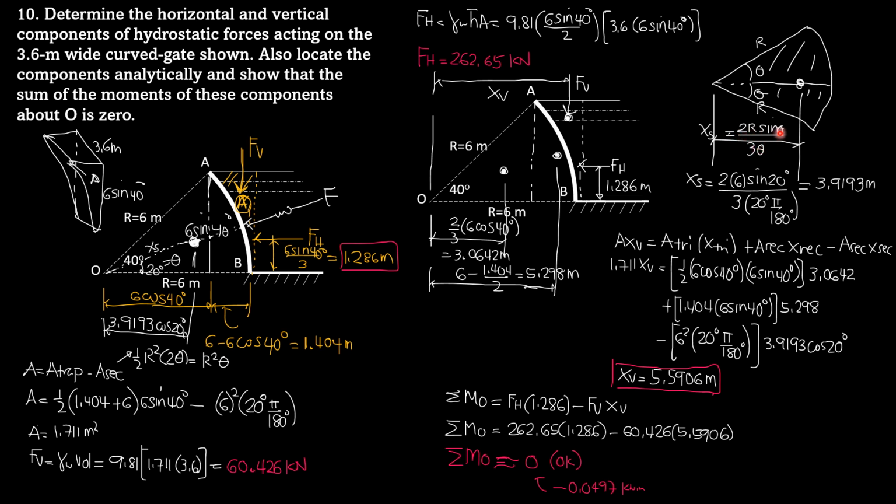You can check that by setting theta equals 90 so that it becomes a semicircle, and it should result in 4r over 3 pi. But theta here in the denominator should be expressed in radians, so that's pi over 2. And you will get 4r over 3 pi. So that's by checking. If you want more about this, you proceed to statics, and the location of the centroid is in that video there in statics, in my YouTube channel.